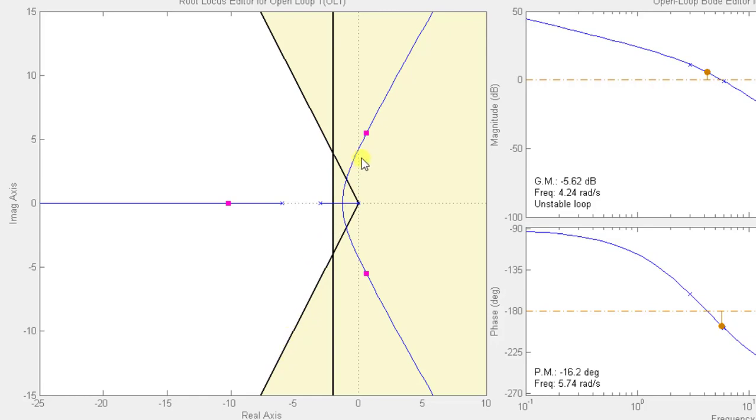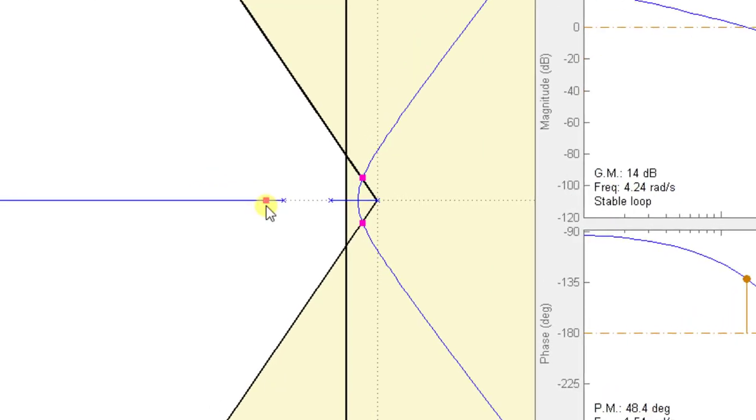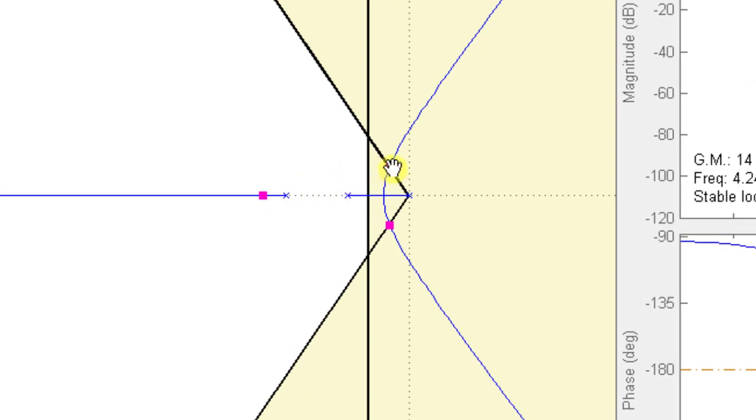So whenever these closed loop poles are on this line, you can have a look that yes, over here you can see that 2 of the closed loop poles, this one and this one, are on it. Don't think that these lines moved, only the view has changed because I've moved these poles. So these poles are now on the zeta lines for 20% overshoot. But what about the settling time? They are far away from the settling time line.